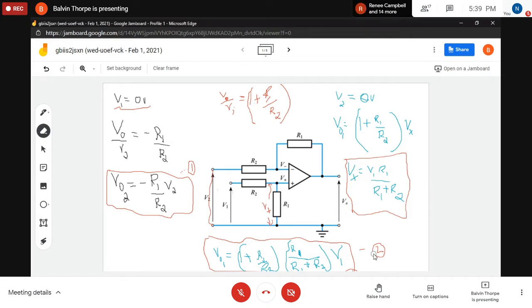That's for the top. Proceed. On the current divider, you have the opposite one. It's a constant. Voltage divider. To find the voltage, you use the corresponding resistor divided by the sum, multiplied by the input. Okay.